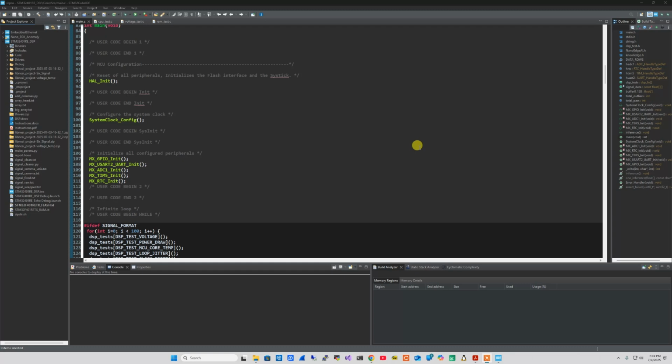And by the way, I'm targeting just an STM32F401RE, so it's not some big high capacity board. I'm amazed at how much functionality I was able to get on this board, and with plenty of room to spare if you lay out your code wisely and use your buffers wisely and make sure you write certain things to SRAM with const qualifiers, and then choose the right model. And this NanoEdge Studio really produces a small model.